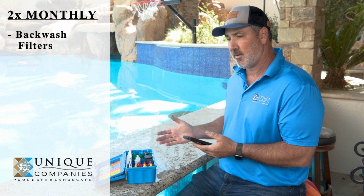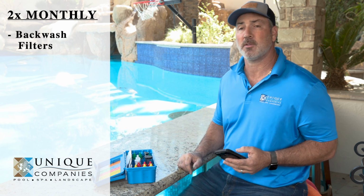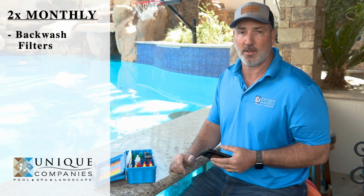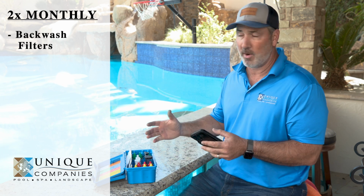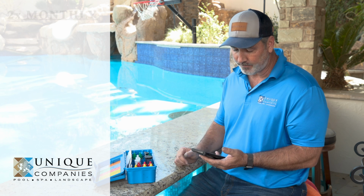And then if you have a sand filter or a DE filter, backwash the filters if that's needed. Most of our systems are designed with cartridge filters because we have the best flow rate as the debris starts to back up within the cartridge filter. So the dirtier our cartridge filters get, they don't reduce the flow rate, so that we have cleaner pools and more horsepower, more flow to our in-floor cleaning systems.